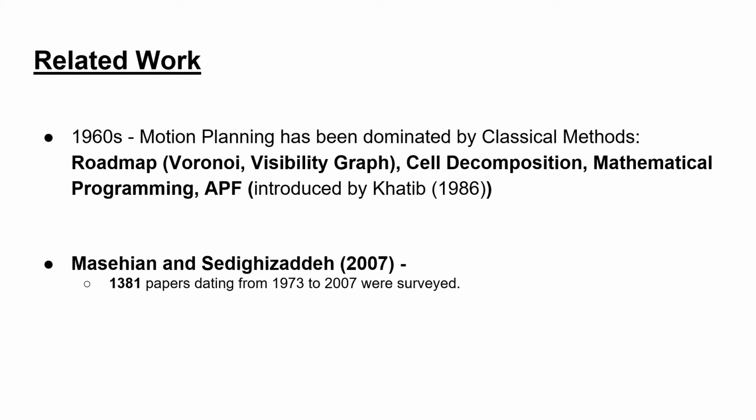At the beginning, this method was used for obstacle avoidance in path planning for robot manipulators, but through time, it has well been adopted for mobile robots and groups of mobile robots. One such example is robot swarm formation, obstacle avoidance, and swarm movement control as a whole using artificial potential fields. In this, an MR, mobile robot, is treated as a point represented in the configuration space as a particle under the influence of the fields.